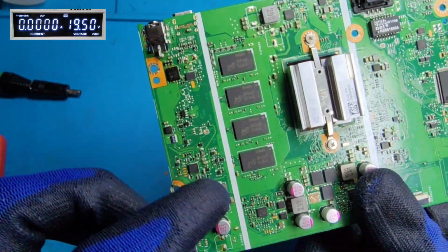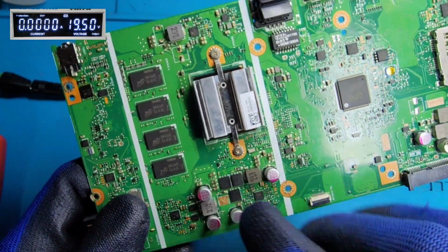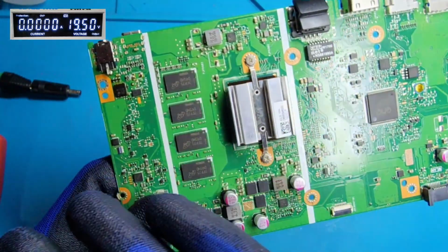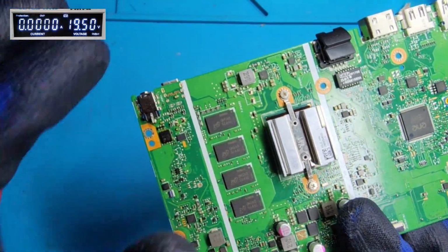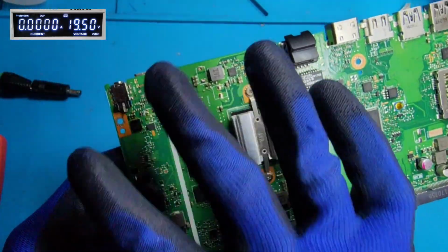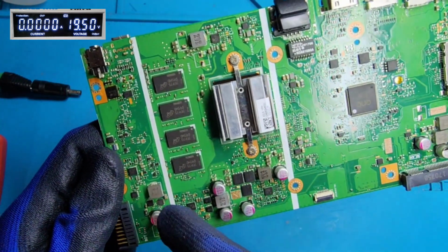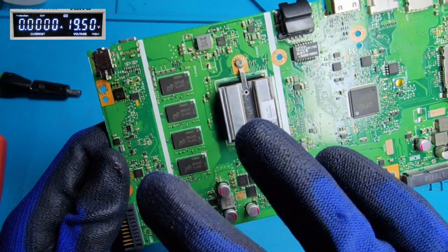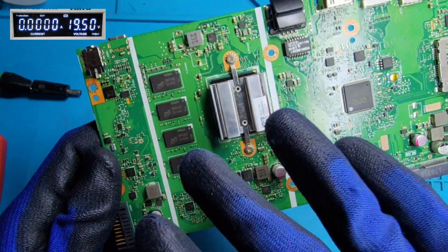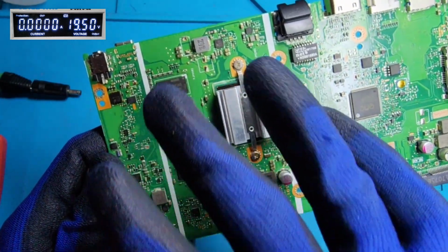There will be continuous 19 volts into the motherboard. Even if any component got shorted, there is no one to protect your components here. Unless your adapter cuts off the voltage, your motherboard will not be safe. So the charger IC is faster than the adapter. It will detect the short on your motherboard, and it will cut off the voltage into the motherboard here.